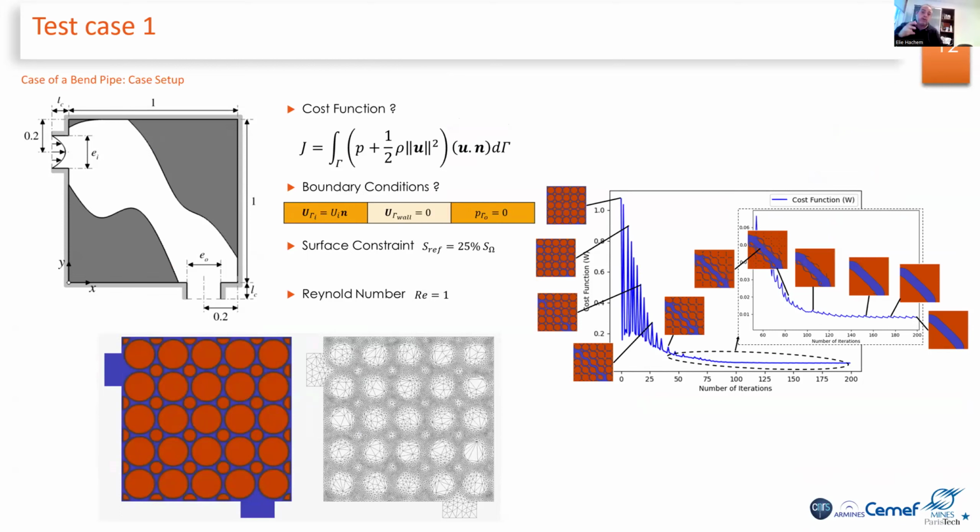To penalize the region of the solid, you can do it in different ways. You can do it as a Darcy term. You can increase the viscosity. If you have a high viscosity in the solid region, it will behave as a solid because you push the rate of deformation towards 0, and it becomes a solid. Also there is a forcing term. In our case, we use high viscosity with Darcy. Both can help.